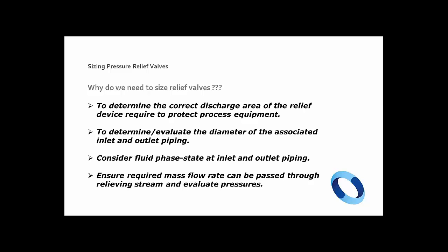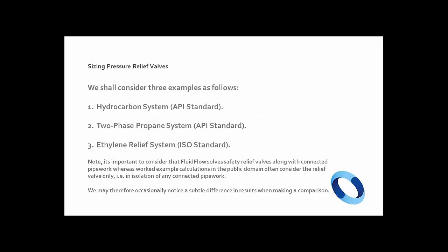And what FluidFlow does is it allows you to model the interaction of connected components, whereas in some cases we have been discussing with engineers where they may have been using Excel or other platforms to perform relief valve type calculations, but that only looks at the device in isolation, not connected to any other equipment. So FluidFlow overcomes that little obstacle for you. Okay, so today we're going to focus on 3 example cases, and we'll build one simple model, and we'll model each of the 3 cases from that base network.